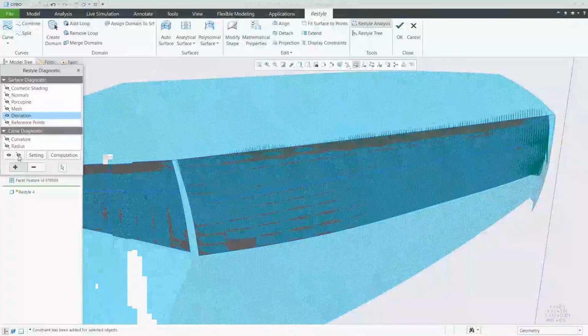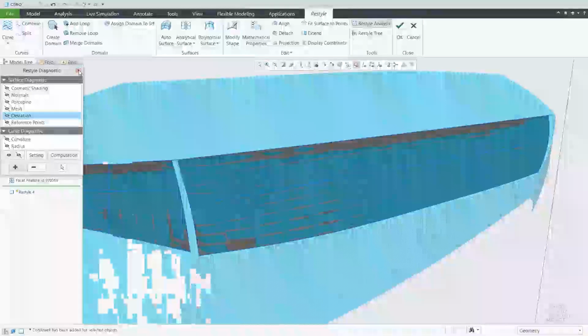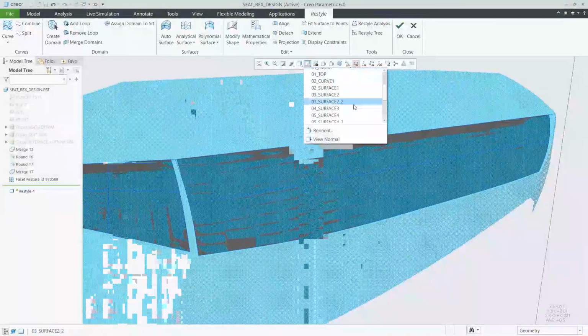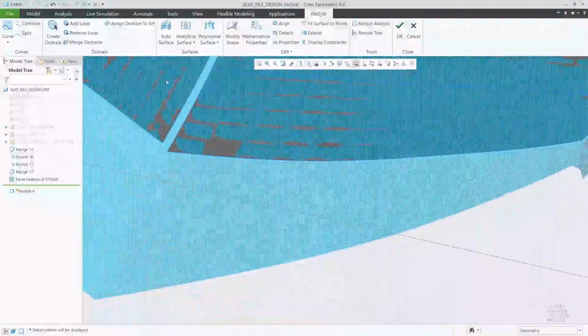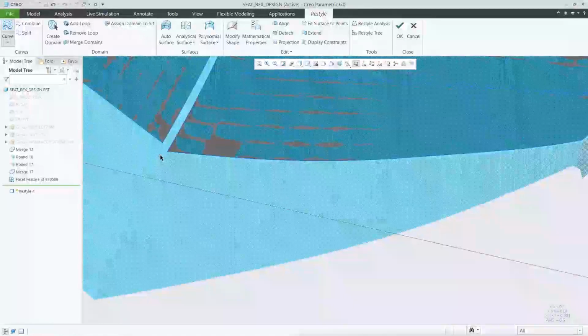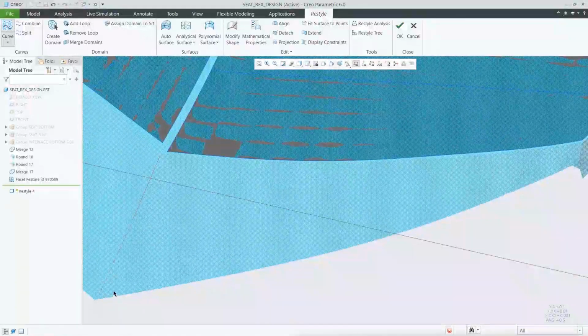So you can clearly see you can go through, build out the surfaces, analyze them to see what you got, really based off of that point cloud data that you started with, but you're not tied to that if you don't like to be. So you can go ahead and keep moving on to some other areas of the point cloud data that we started with here. Let's go ahead and create another surface down here.